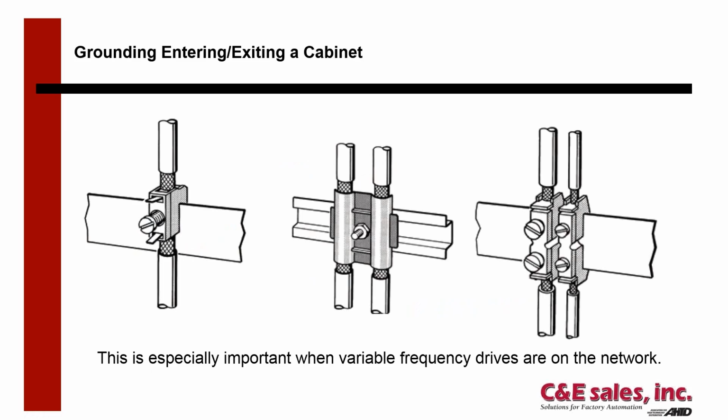The older Siemens drives, the 6SE70s, the 6RA24s, the 6RA70s, they were notorious for having the communication board tucked in right underneath, right next to the power interface board, and it was just a complete noise. It was just a terrible environment. So on those drives, they actually have a special place on the chassis where you can remove the insulation of the Profibus cable and take that shield to the ground on that drive, and hopefully that drive is grounded appropriately. And that takes care of a lot of noise.